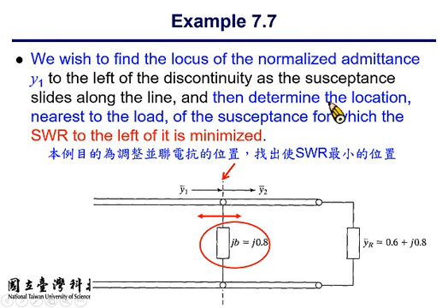We are not aiming to achieve perfect matching as we have done last Friday. Last Friday, we demonstrated that you can do perfect matching by using the single stub or double stub matching technique. However, even though you can achieve perfect matching, it's only valid for one single frequency.